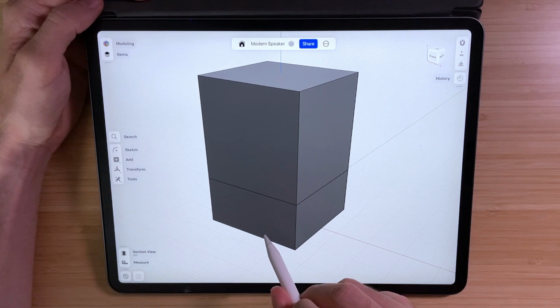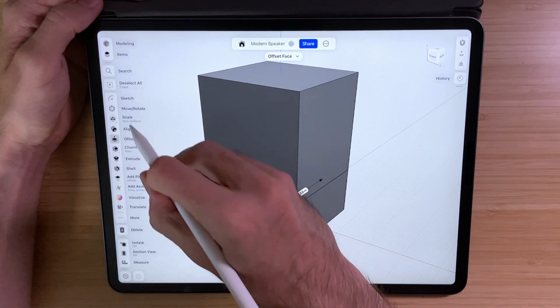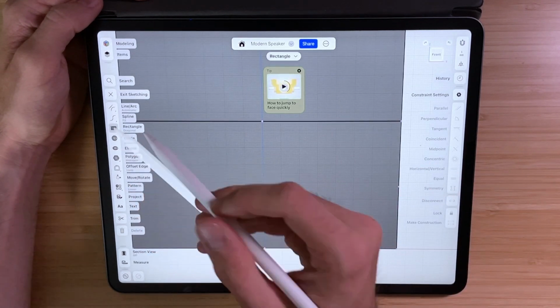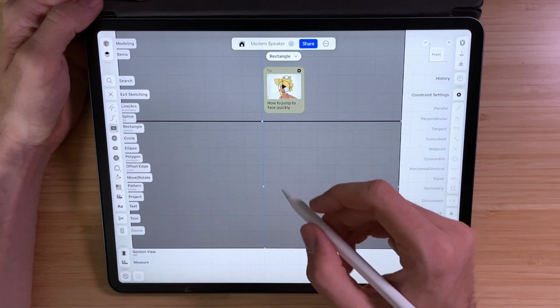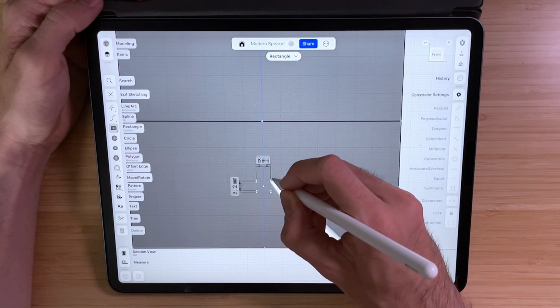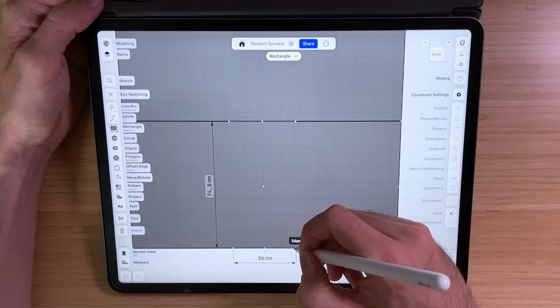As the next step, we want to do the same thing with the lower part. So select this surface, go to sketch, and again, we'll create a rectangle, but this time I'm going with a center rectangle, and then go from this projected center of our rectangle to one of these edges. I'm selecting the lower because it's easier to grab.